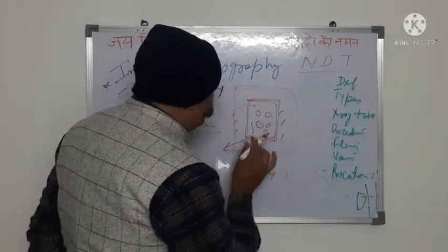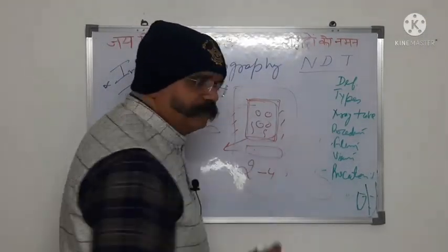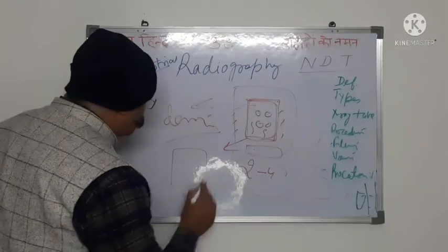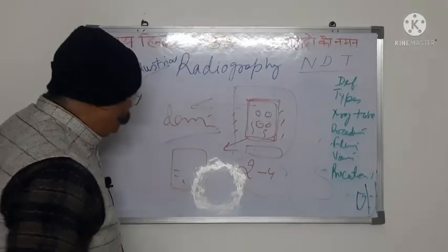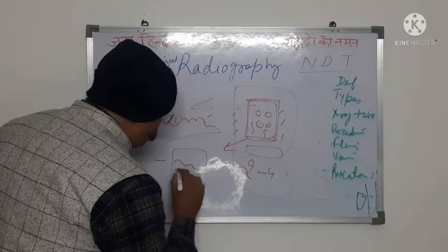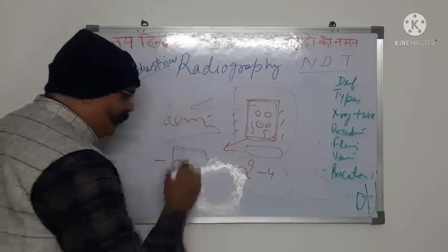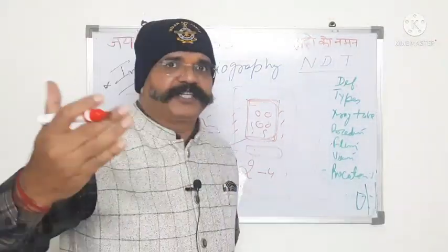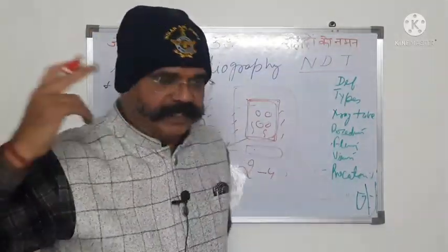This darkness should be in a certain range, because if the X-ray film is not much darker, it may not carry the defects over the X-ray film, because sufficient penetration of the material would not have taken place.